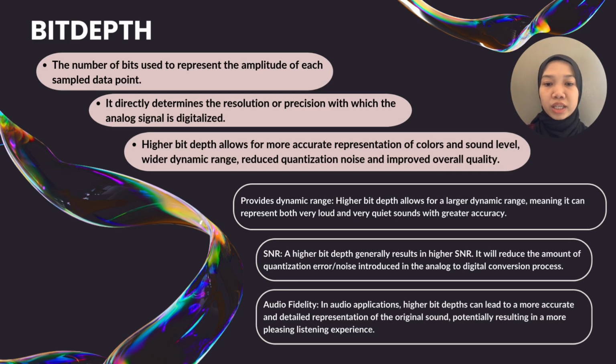It provides dynamic range. Higher bit depth allows for a larger dynamic range, meaning it can represent both very loud and very quiet sounds with greater accuracy. Next is the signal to noise ratio. A higher bit depth generally results in higher SNR. It will reduce the amount of quantization error or noise introduced in the analog to digital conversion process. Lastly is the audio fidelity. In audio applications, higher bit depth can lead to a more accurate and detailed representation of the original sound, potentially resulting in a more pleasing listening experience.